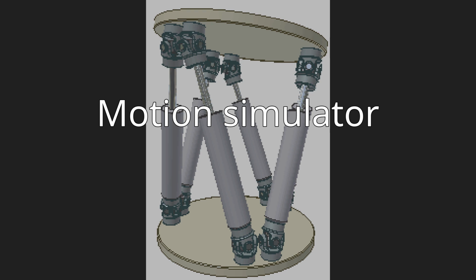Motion simulator. A motion simulator or motion platform is a mechanism that creates the feelings of being in a real motion environment. In a simulator, the movement is synchronized with a visual display of the outside world (OTW) scene. Motion platforms can provide movement in all of the 6 degrees of freedom (DOF) that can be experienced by an object. These are the 3 rotational degrees of freedom: roll, pitch, yaw, and 3 translational or linear degrees of freedom: surge, heave, sway.